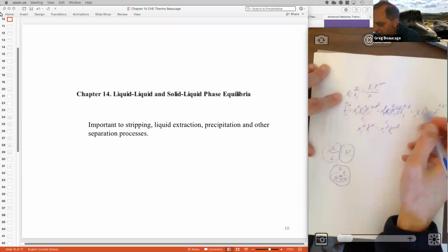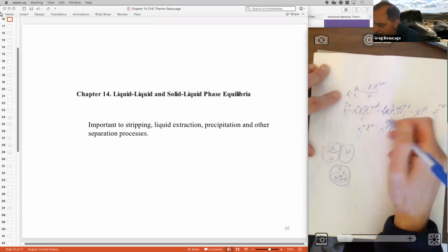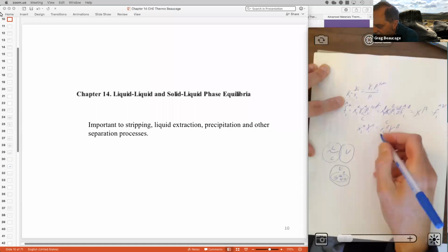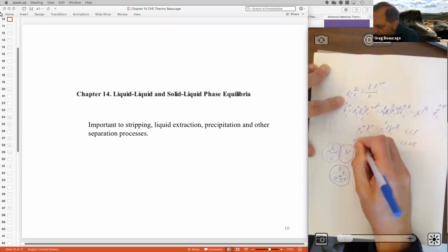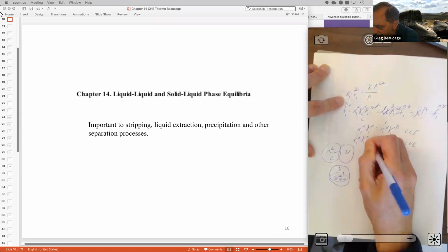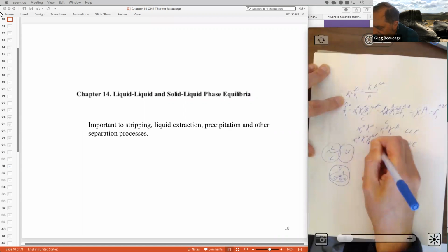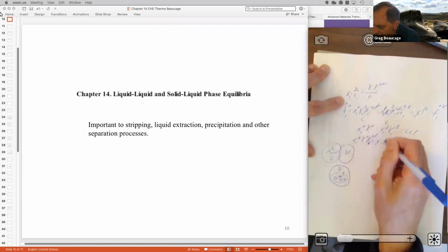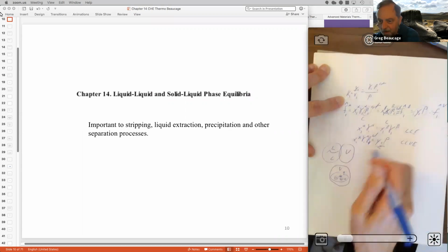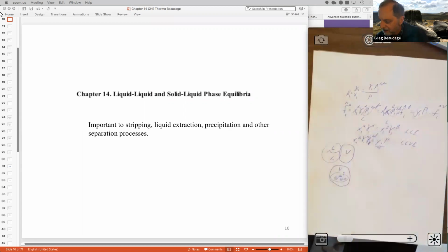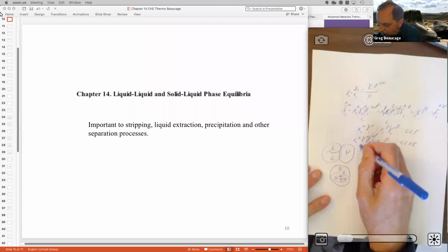Right? So in that case, this is liquid equilibria. If you have liquid vapor equilibria, you have to use x1 alpha, gamma 1 alpha, p sat 1 equals the same for beta equals y1 times p. So you have to keep the p sats so you can get the vapor part of that. So that's when those are all at equilibrium with each other.